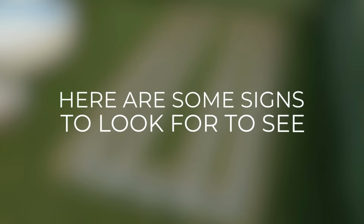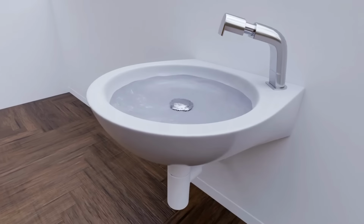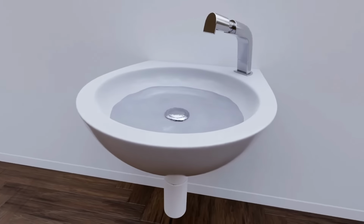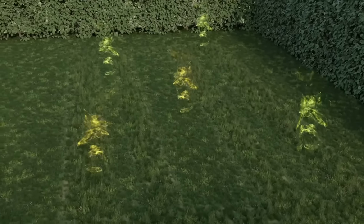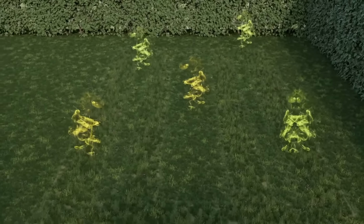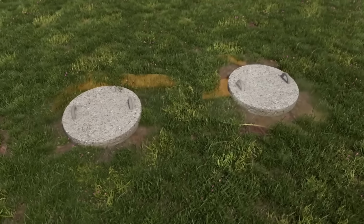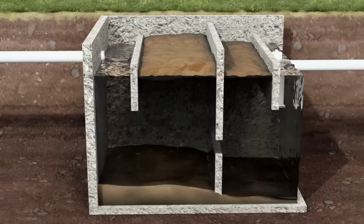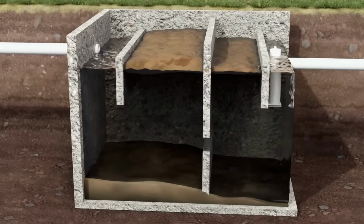Here are some signs to look for to see if you need to unclog your leach field. Before the drain field stops working completely, you may notice that the water is draining more slowly through the house. Septic tank odors can be present near the leaching field or inside the house. If there is no space left in the septic tank, the wastewater will back up through the opening or into your home. If you notice an abnormally high water level in the septic tank, it is almost certain that your leach field is at fault.